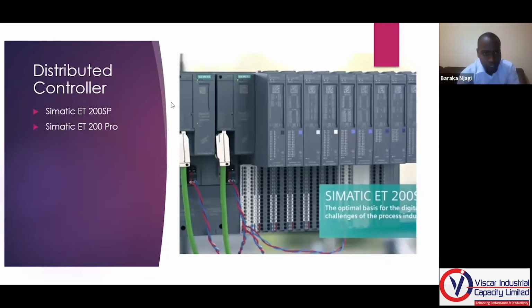Siemens have their own that they call Simatic ET200SP or ET200 Pro. So what happens is, from the sensor, it connects to this ET200SP, either through the signal cables that you're seeing there, the blue and green cables. And then from this, a cable can run using either Profinet or Profibus. I'll show you those kinds of cables in a few slides. And all this runs up to the main CPU. Then the CPU, the one hosting the program, can interpret what needs to be done and actuate an output. So these are the distributed controllers.